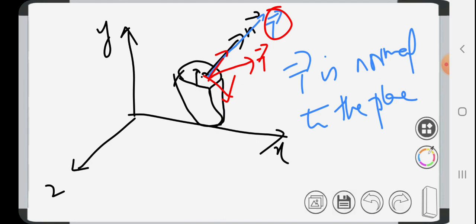So what is the plane on which the normal stress is a maximum? What is its magnitude? In this case, the t vector is wholly normal and there is no shear component, only a normal component. So the normal stress is maximum in this case. What will be its magnitude? What is the plane on which the tangential or shear stress is maximum? And what is its magnitude?